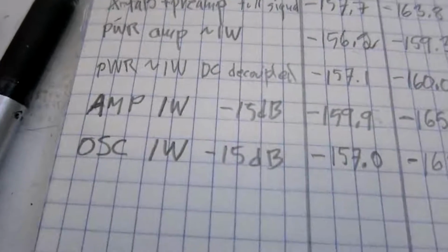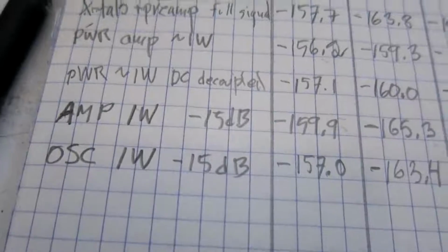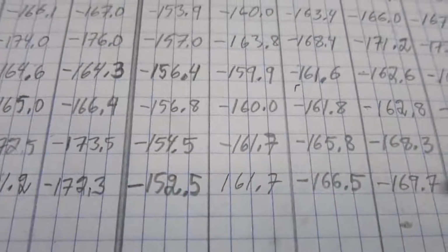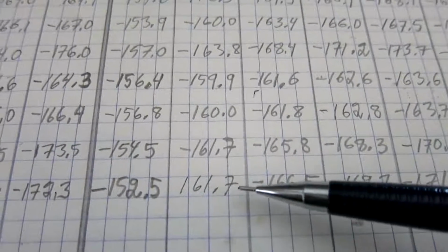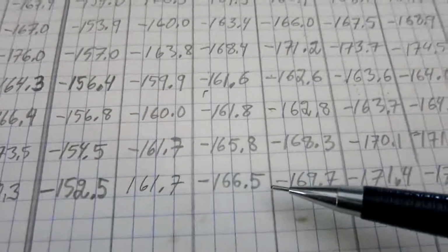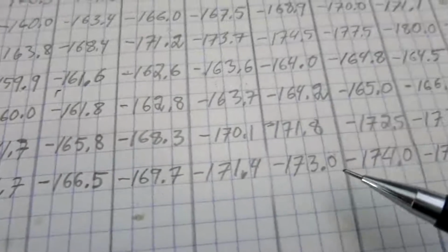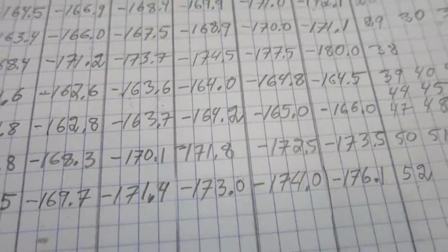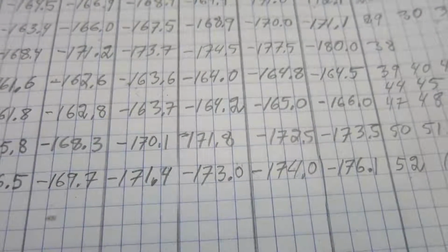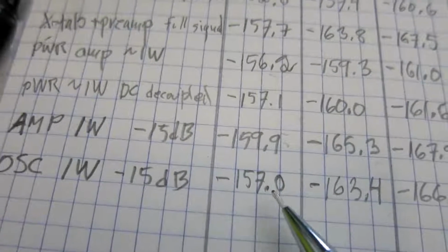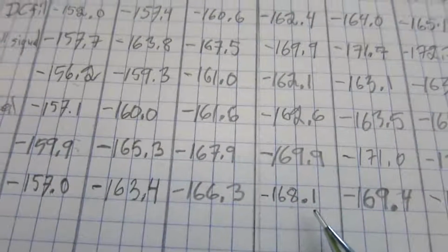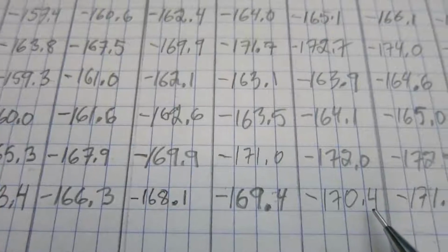So I compare the unit running it as an oscillator and as an amplifier. And I look first at the phase noise here, and I find that as an oscillator it is not quite as good at 50 Hz, but at 100 Hz it's the same, and at higher offsets the oscillator is better than the amplifier. Because the filter is removing phase noise that is present in the Wenzel oscillator. But looking at the AM noise, at close range it is degraded by about 1 dB, but at wider ranges it's degraded by 2 dB.